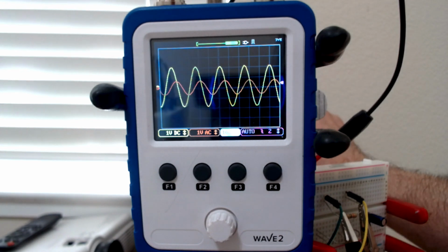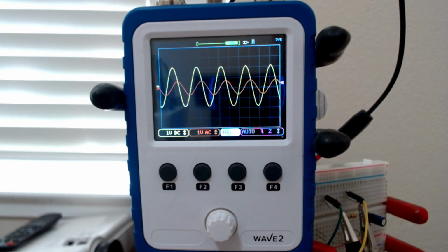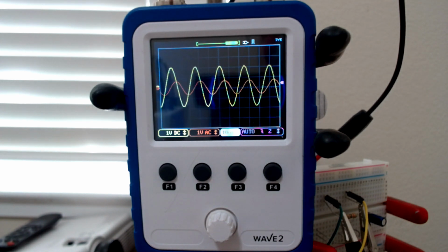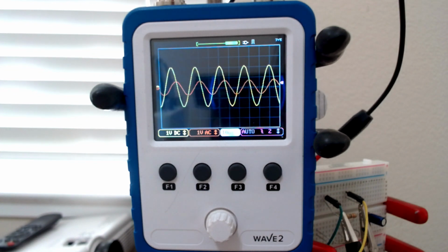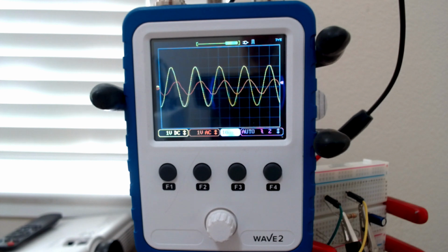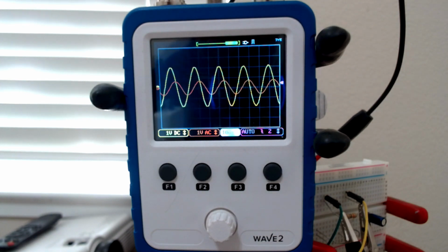Now I'm at 40,000 hertz. Notice that there's a phase shift of almost 90 degrees between the resistor and the power supply. Can you all see that? The little orange one? That's essentially a 90-degree phase shift between the two. And as I reduce the frequency down to 0, the resistor will dominate in the circuit. So Morgan, in this particular circuit, because I just have an inductor and a resistor, 90 degrees will be the maximum.